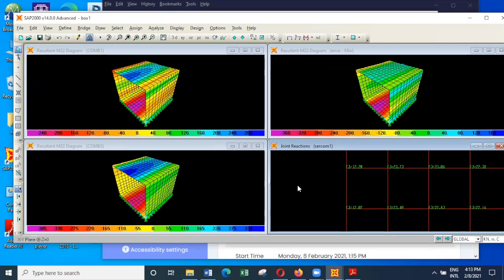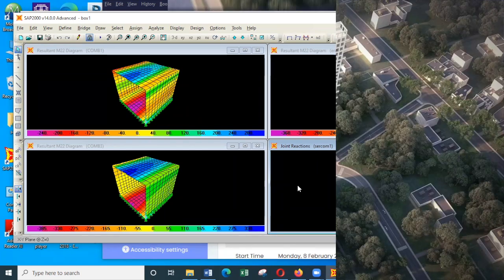And then you can design the reinforcement as per BS 5400 Part 4. But the difference is that the crack width has to be limited to 0.25 millimeters, not 0.3 millimeters. So you have to calculate the crack width and show that it is limited to 0.25 millimeters in highway structures. So any question you want to ask? Or is it clear? Yes, sir.